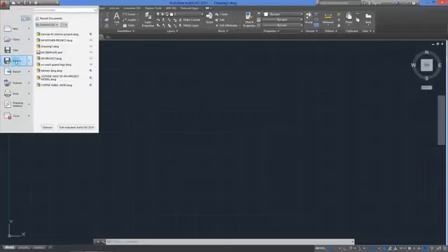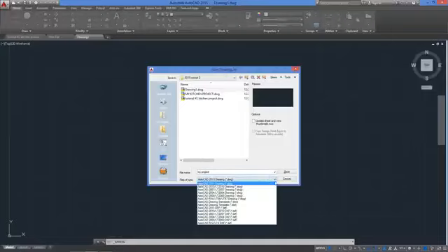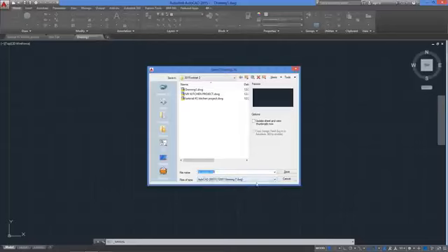Now, when we're doing so, a caution note, if you will be sharing this with someone else, is to save the drawing in one of the previous versions that the other person will be able to open. Pull the list of available options from the File Type drop-down menu and use the one compatible with the other person's CAD, like AutoCAD 2007 or a different one.